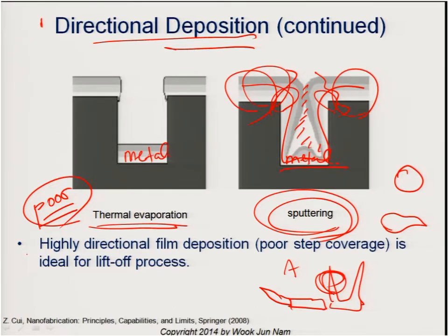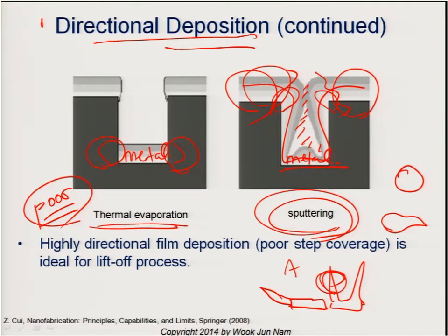We will talk about how to make these undercut structures. Actually, making an undercut structure is getting tougher as you move toward advanced lithography technology, because in that case the pattern size is much smaller. So you need very precise control of dissolving these underneath layers.